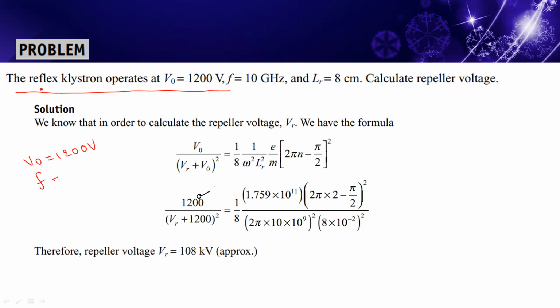Frequency they mention, 10 gigahertz. So value LR equals to 8 centimeters. Calculate the repeller voltage.